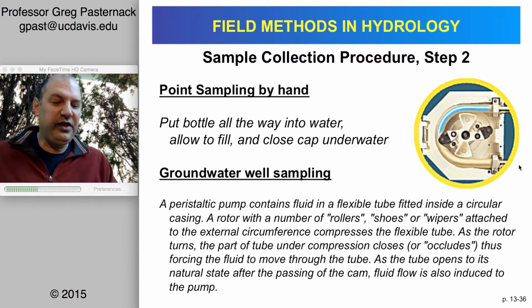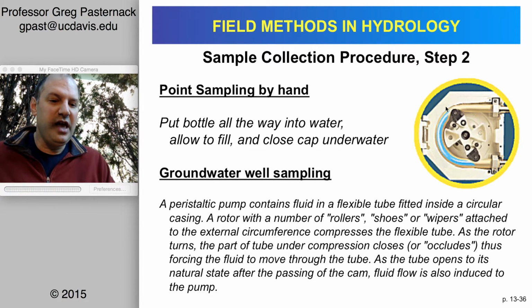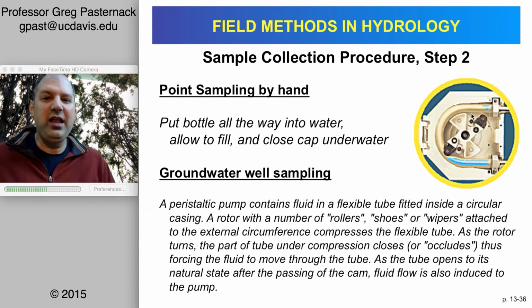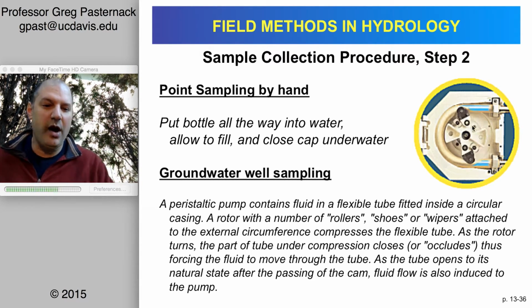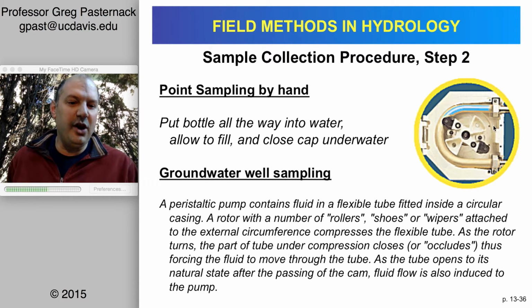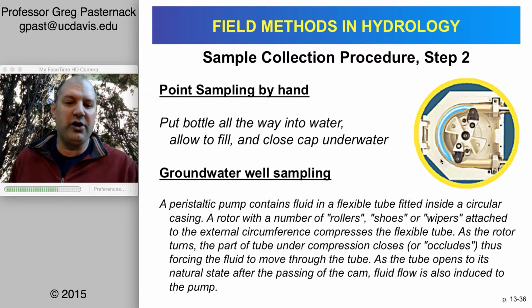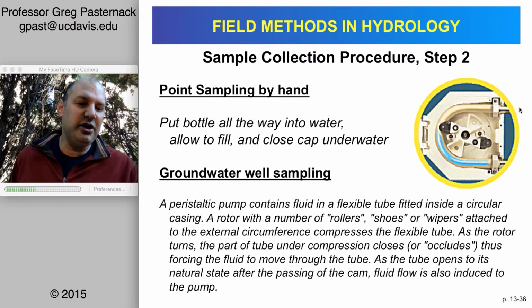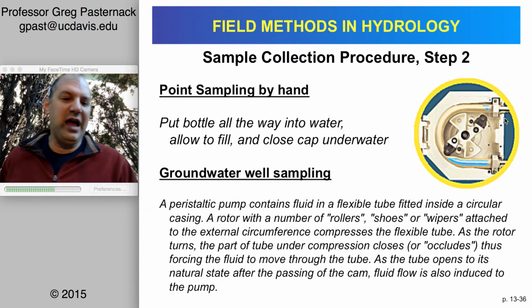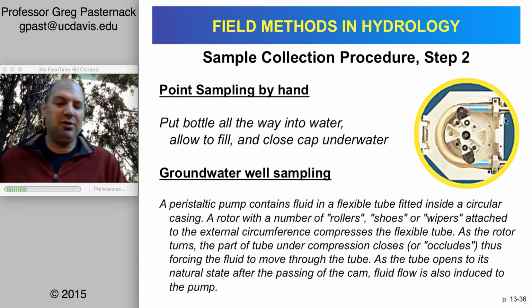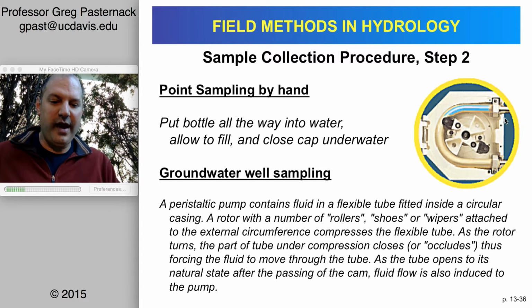So what this does is it pinches a rubber hose, and when it does that and it moves, then that's creating a pressure gradient that sucks the water up. And on the other end, when it opens, then it's literally pushing the water with the second one. So it's a pressure-based pull, and then a direct push to get the water in and out. And so that can then draw the water around.